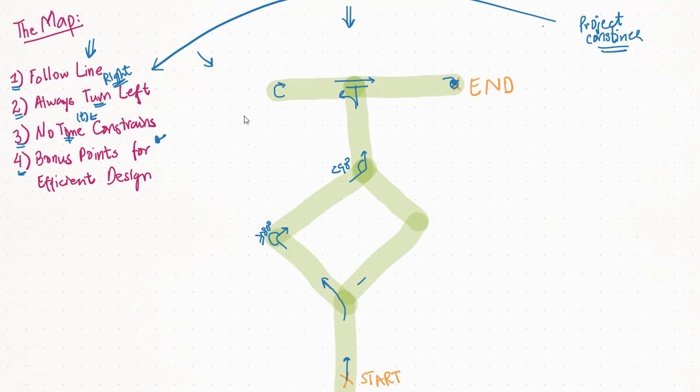So now let us talk about the strategy, the logic we would be using to navigate our robot through this path. Some people prefer to use two sensors for line detection, and some prefer three sensors or even more to detect the line and navigate the robot. But I don't think that it's necessary to use more than one sensor. You can get this done with just one sensor.